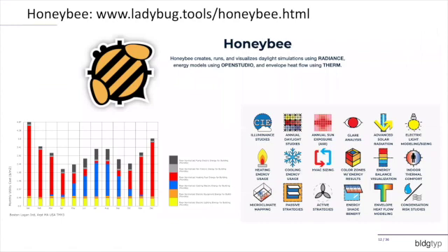recording those results. Now, briefly, Honeybee is the name of a set of open source free tools, which are pre-made Grasshopper definitions, and they give us the power to create an amazing array of building simulation and performance assessments. Things like daylighting, thermal comfort, glare, condensation, envelope thermal performance with THERM. All of these things can be assessed and visualized using this really powerful toolkit. In addition, Honeybee creates Energy Plus dynamic models from Rhino geometry. So we can use this existing framework. We don't have to reinvent this at all.